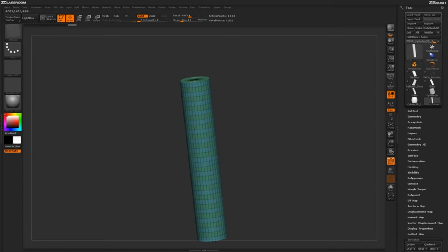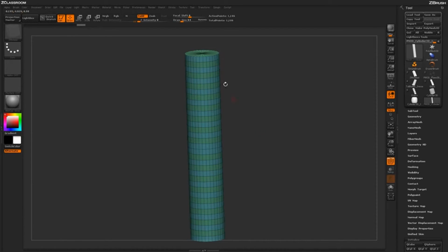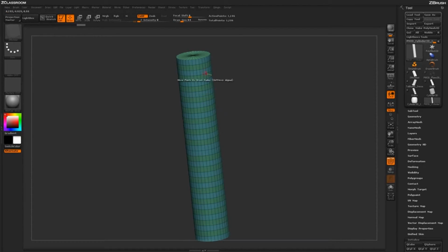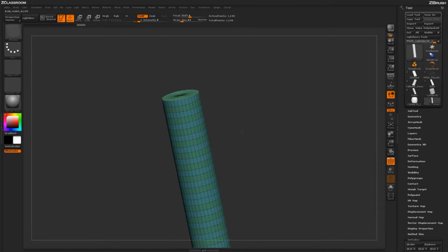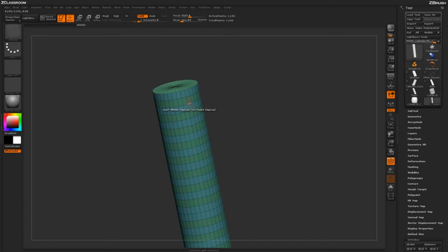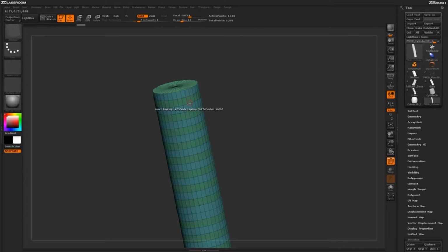Now I don't need this much edge looping established, but I basically wanted to make sure that any single area where I have this joint section being created, it's a consistent size. So I'm actually going to come through now and remove some of these excess poly loops here that I no longer need. So to do this, I'm going to hover over an edge again, press spacebar, and now select a single edge loop. And now if I hover over an edge and while holding Alt, click, I can come through and start removing some of these actual edge loops on my model.